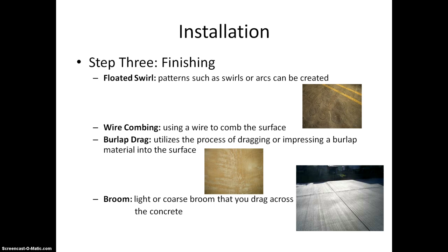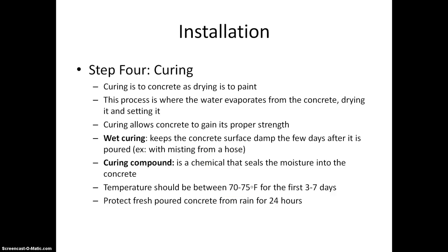And then there's also other types of finishes if you want an aesthetically pleasing look for like the interior of your house, but we'll get into those later. All right, step 4 is curing. Curing is to concrete as drying is to paint. This process is where the water evaporates from the concrete, drying it and setting it. Curing allows concrete to gain its proper strength.